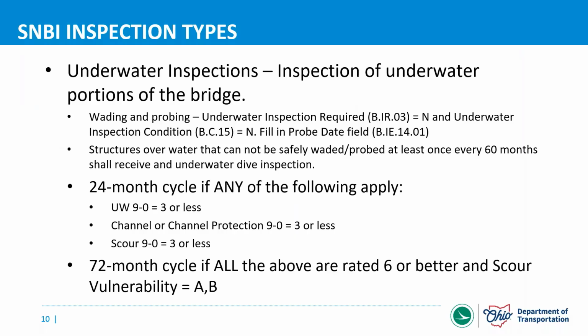Again, that is a federal metric that is tracked. So if that underwater date changes, we will be making sure that substructure units in the water were safely inspected. But just keep in mind that there have been cases where water levels have dropped a lot, where maybe it's typically at 6 feet and we're never able to probe it, but now it's at 2 or 3 feet for some reason.